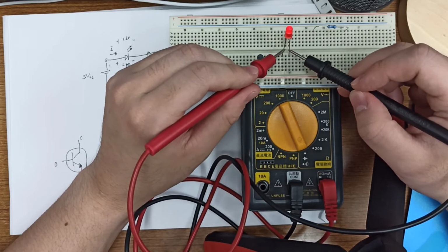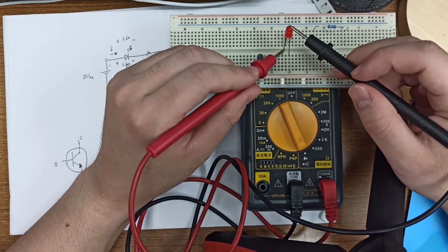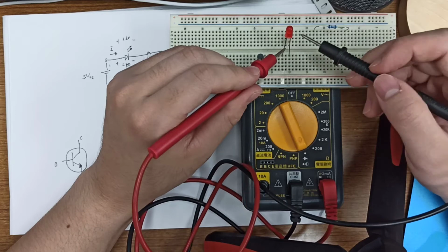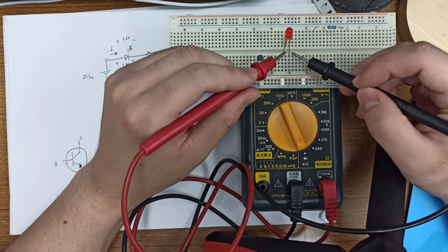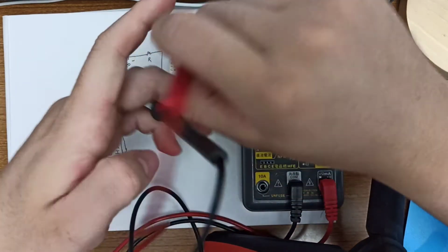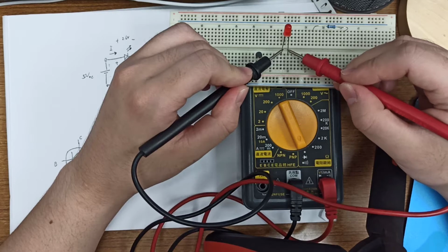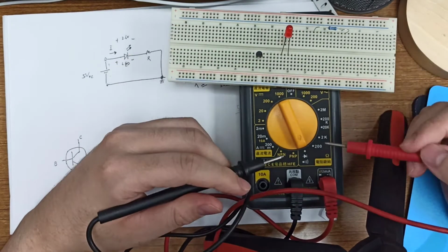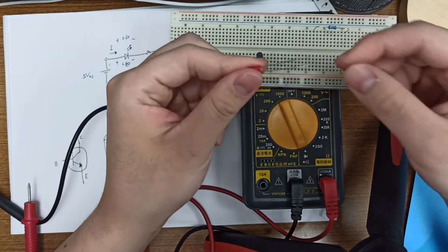If we use the diode check, we can check the positive of the LED. No matter which diode, we can use the same way to check. If this one is positive and this is negative, and in the other direction it will not light, so we know we have the wrong direction. So this is the way to check the LED if you don't know which one is the positive pin and the negative pin.